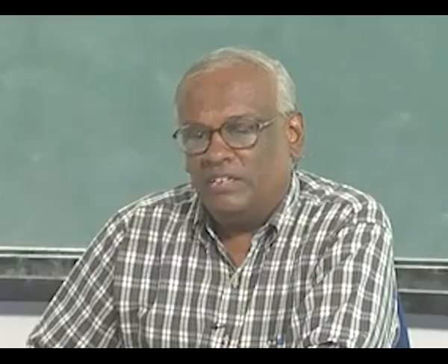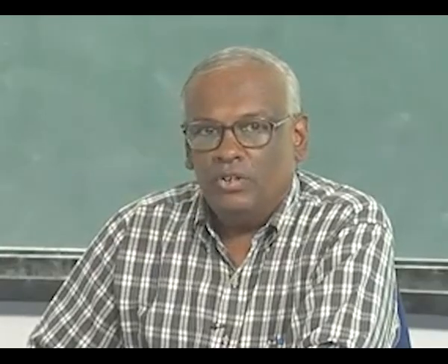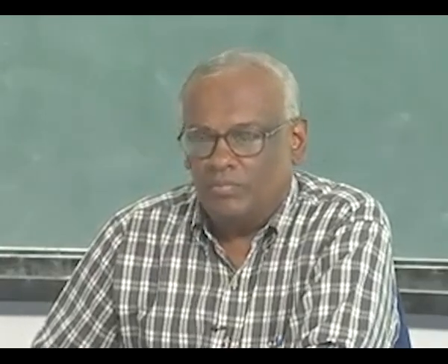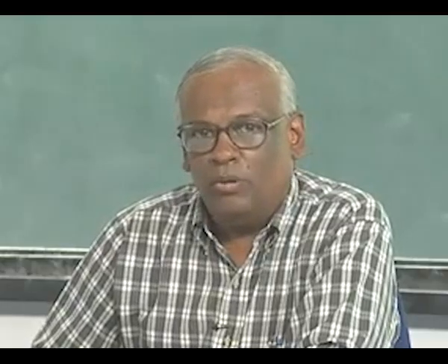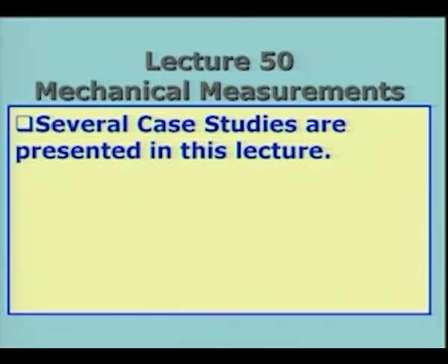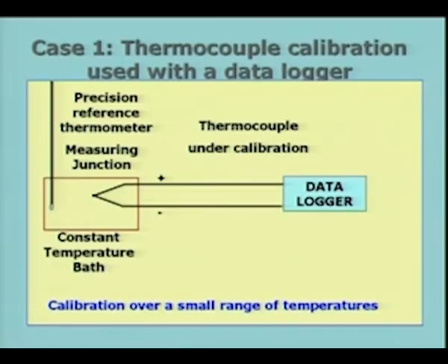So, in the present lecture, what I will try to do is to look at a few cases and then see how we can go about making the measurements and also choosing the right kind of instrument for the purpose of making the measurements. So, the first example I am going to take is with respect to calibration of a thermocouple, and I am going to discuss how it can be done when a data logger is available to us.